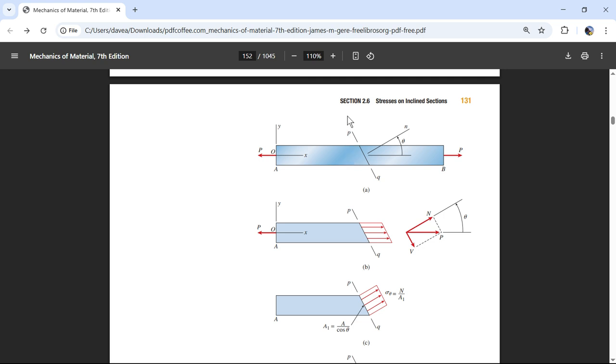And so if I put 29,000 pounds perfectly perpendicular to this 1-inch steel rod, I could shear it apart. Now this being 70% of 58,000, I wish I knew that number, it's going to be bigger than 29,000, but it's shearing on a larger surface. So the pressures that get developed are still 29,000 psi, which is the max that steel can take.